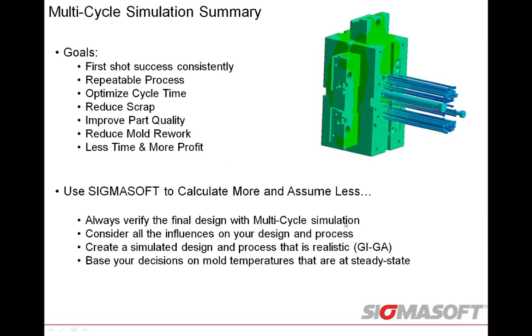A lot of our customers will start out with maybe just the part itself. Start early, when they have the information. Then as you gain information through the process, keep bringing more and more of that into the simulation, and do your final verification. Make that part of your process. Doing multi-cycle simulation with your components, and really understand what's going to happen. So when you build that tool and put it in production, you're much more prepared.